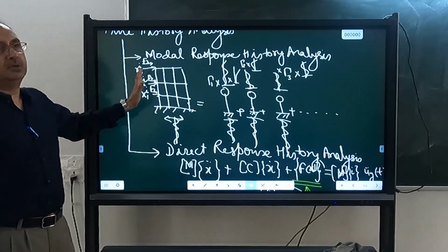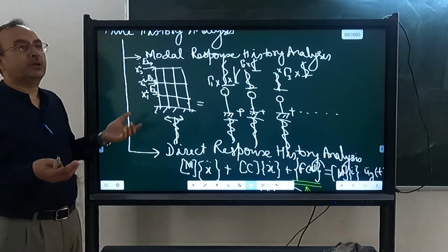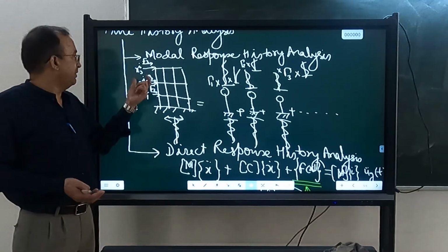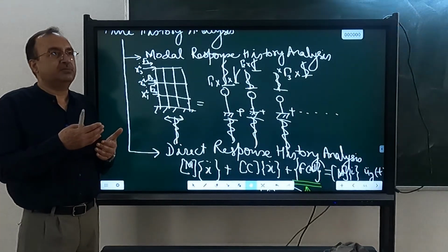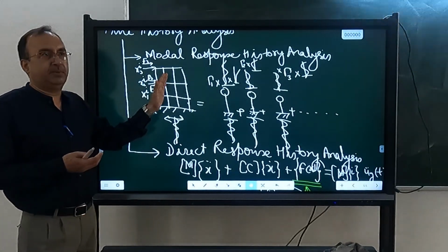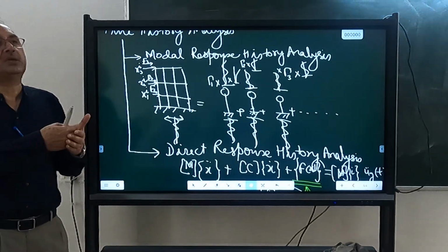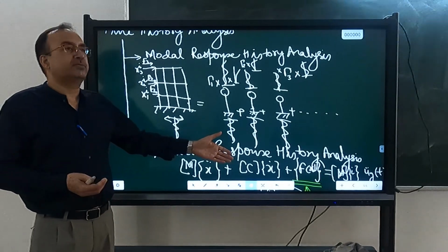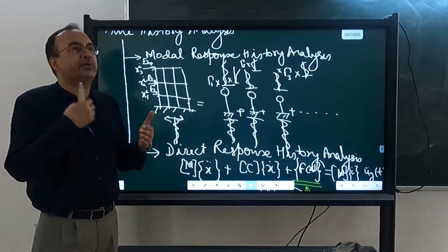We can reduce the speed because then the cost of the actuators required will reduce. We will not need such large actuators, because the size of the actuators depends not only on the force we are applying, but also on how quickly that force is applied, at what frequency it is acting. Earthquake forces, earthquake acceleration and displacement require very high frequency.